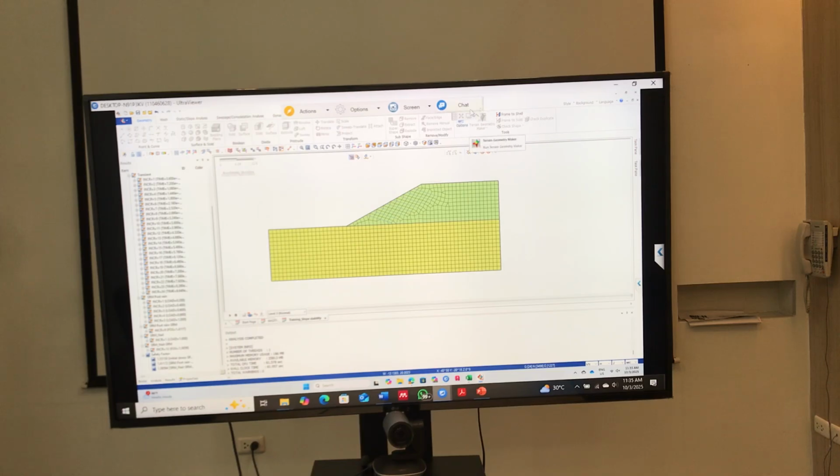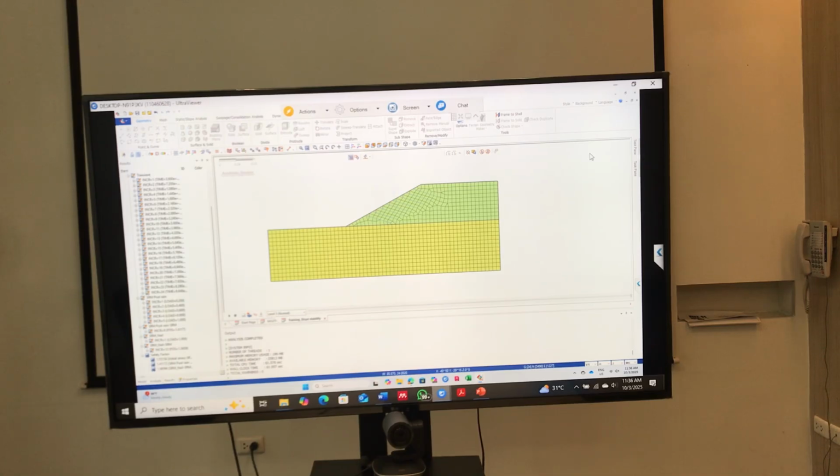It's also here. I can see it. It's somewhere here. Yeah, so you just go to interface, and when you are defining interface parameters, there is what we call normal stiffness and shear stiffness. So those are defined based on Mohr-Coulomb also. So you try to get the materials from the adjacent layer. For example, if the interface is between soil and concrete, you can use the material properties of soil, but there are some equations that you use.